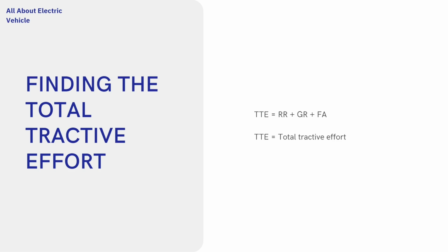The total tractive effort is an important parameter in electric vehicle design because it determines the torque required for the electric motor. The electric motor must be able to provide enough torque to overcome the total tractive effort in order to move the vehicle. Therefore, by calculating the total tractive effort, we can determine the requirements for the electric motor and select an appropriate motor that can meet these requirements.